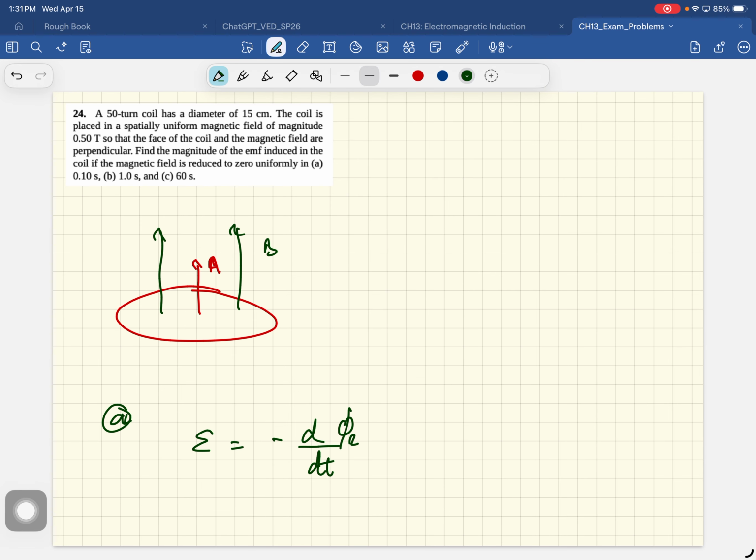Why are we doing this? This is an induction problem. In an MRI machine, you see fields like that, and you just can't switch off the MRI machine just like that. You would induce currents in current loops, at fairly high voltages. So you want to quench a magnetic field slowly. If you have a strong magnetic field, you want to turn it off to 0 slowly.